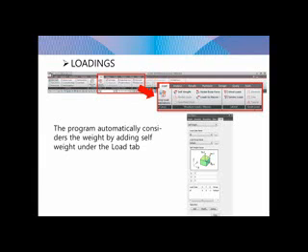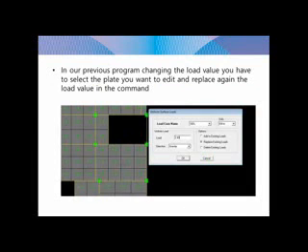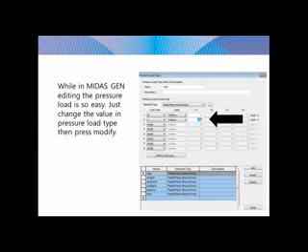These are the loads. We have the static load. Under the static load, we have the dead load, live load, seismic, and wind. Now, for the seismic earthquake load, in our previous program we only had earthquake along X and Y. We can get the angle of excitation of the structure. Now we have earthquake major and earthquake ortho. It is seldom we find software that can compute the angle of excitation.